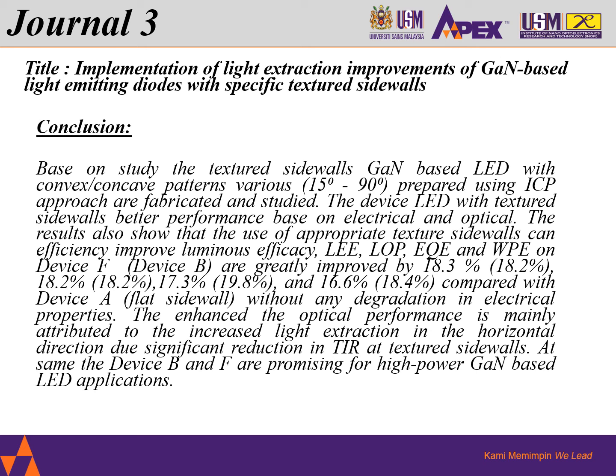The achievement of the optical performance is mainly due to increased light extraction in the horizontal direction, due to a significant reduction in TIR by the structured sidewall. At the same time, device B and device F are promising for high power GaN LED application.